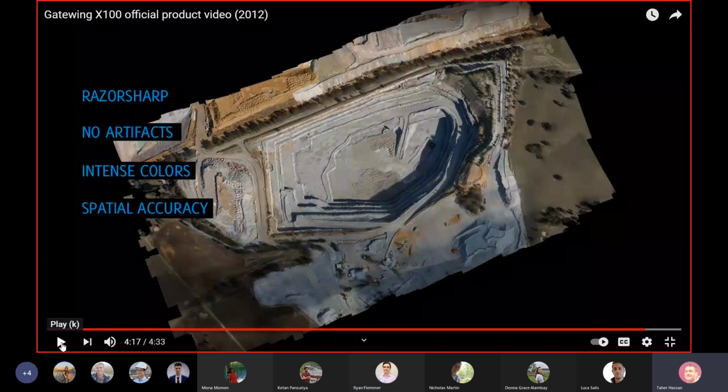And remember, there is some machinery like dozers working their way, and this is a completely unsafe process using GPS or total station, where you have to be physically on the point. While using photogrammetry, it simply saves you all that and makes the process entirely safe. I'm hoping that you guys understand that.